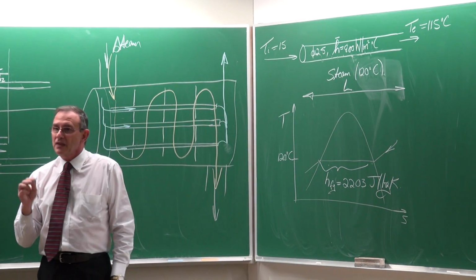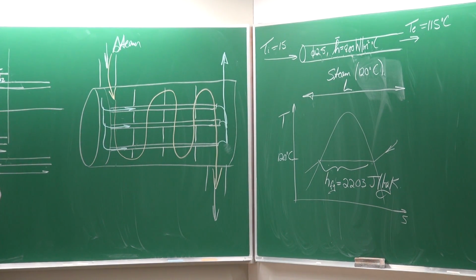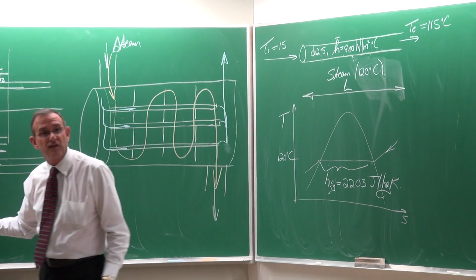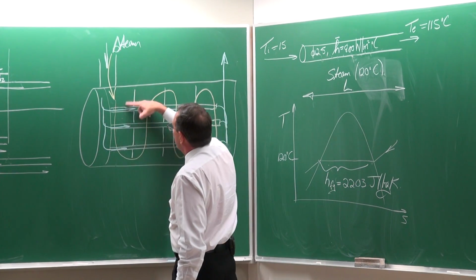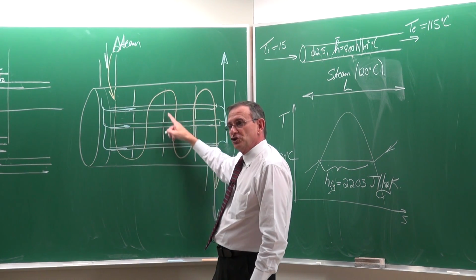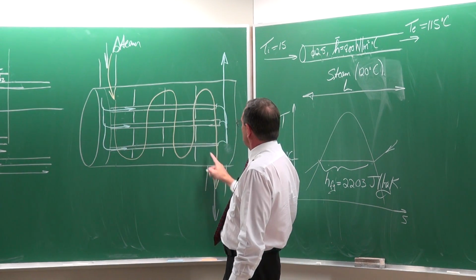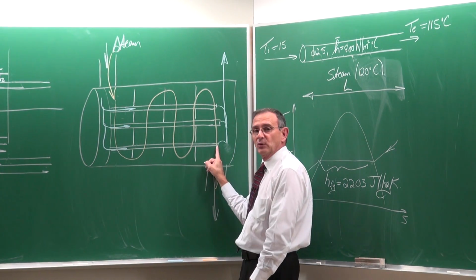Therefore, what is sort of magic or special about the heat exchanger where we have two-phase flow is that when it starts to condense here on the outside, everything here is going to be gas, and it's going to change, and it's going to become more and more liquid until, at that point here, everything is liquid.